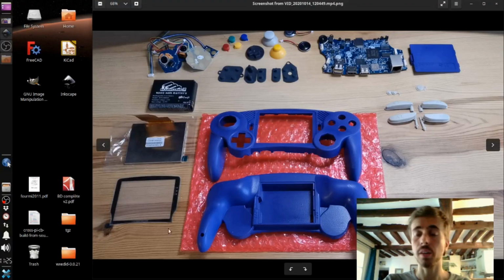So here we have all the different components that make the RetroBlock2. So the first category of components are the 3D modeled parts. So you can see, for instance, the front case here, the back case, the buttons, the battery door, but also all the buttons and all the silicons. All those are actually made on parametric 3D modeling software. I didn't make all the buttons and also some silicons. These are actually pre-existing parts that I purchased directly. So actually I make only these silicons for the L and R buttons and all the other plastic parts.